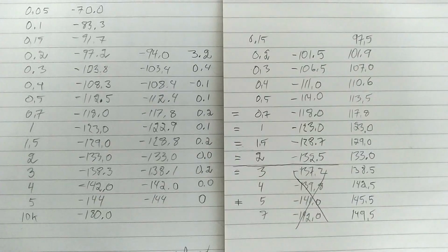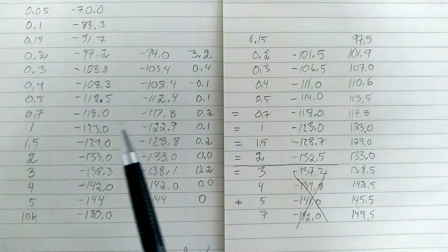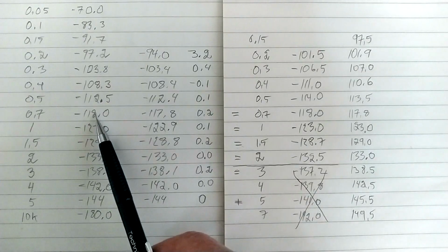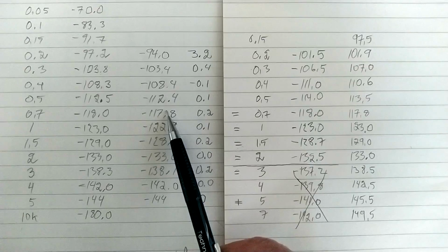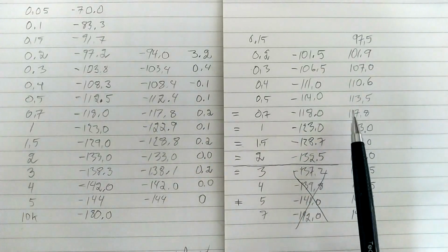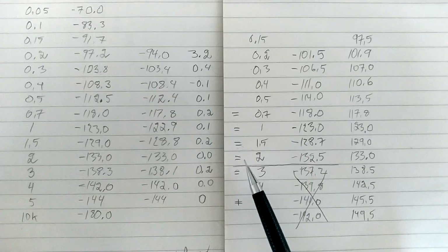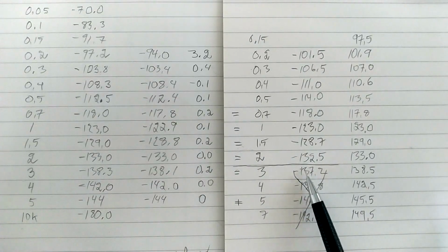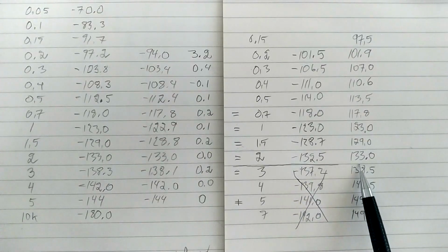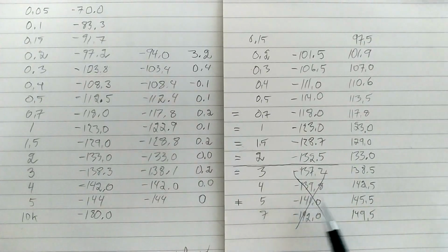When I compare the results I have now with the previous measurement, before I tried to optimize this time, I see that there is no difference above 0.7 Hertz. The two types of measurements I do simultaneously here and here, and they don't differ. And that's correct all the way up to 2 Hertz. At 3 Hertz, this measurement is disturbed by this frequency jump, so I have to look here, and then they are equal. But at 5 Hertz, there is a small difference, 1.5 decibel.